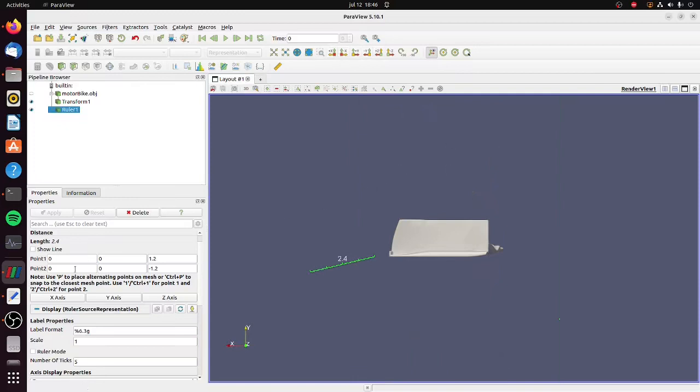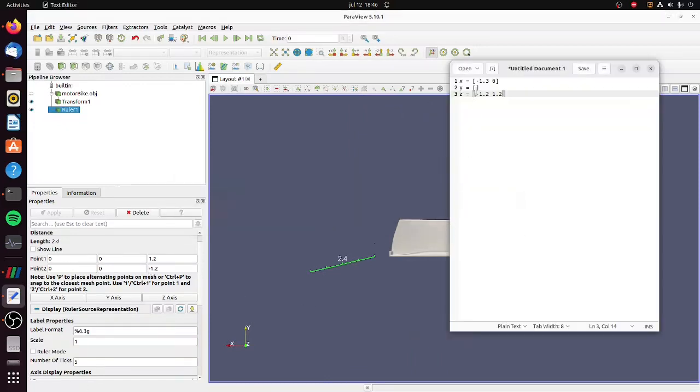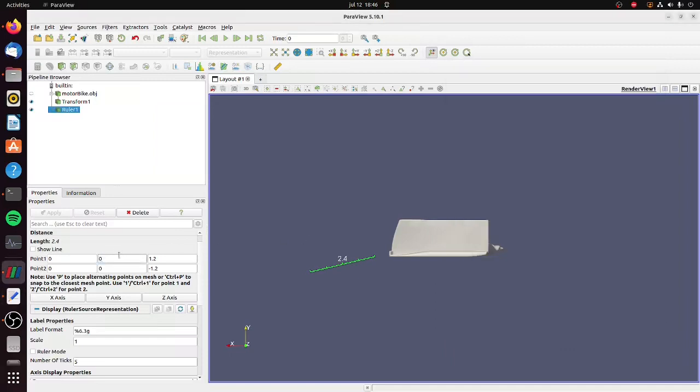Let's again, so the y minimum value will be 0 because we want to use that as the floor, similar to how they did it in the motorcycle case. That's great. And as for the positive value, we just sort of, let's find out. Let's try 0.5. Yeah, should work. It's a little bit high. Maybe go 0.4.